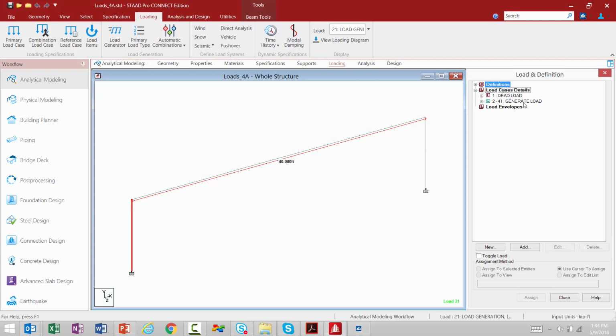Now I've identified load case number 2 and load case number 21 as my worst case scenarios for things like moment, shear and displacement. Load case number 21 is when basically the load is dead center, at midspan of my portal frame. Load case number 2 is basically the starting point, when it's at the end of the bridge structure.